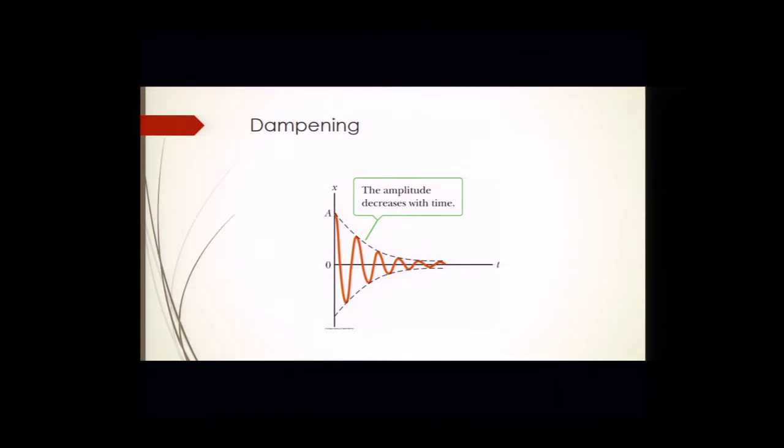Now we also know, because friction drives us all crazy, that friction is our friend and friction is our biggest enemy. That's why the second law of thermodynamics is a pain in the tush. That's because we're going to lose energy due to friction more than anything else. But if I'm bouncing up and down in my truck, and I've got the old classic shock absorbers and the old classic spring, and my shock absorber is starting to go, what's going to happen to that lovely shock cylinder? It's going to leak, and eventually I'm going to bottom out and I'm going to break something.